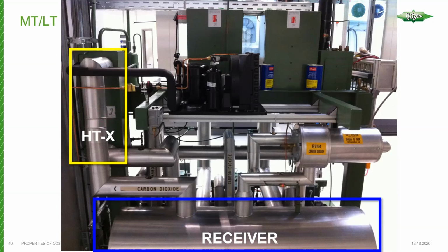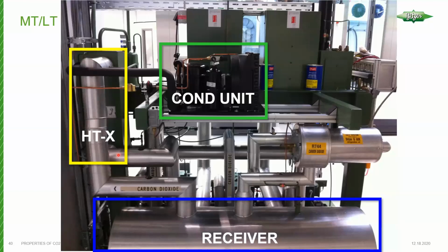And so you could have your pressure transducer determine that the receiver pressure has increased above some pressure such as 450, 500 PSI or so. That would initiate a condensing unit operation here, which would then refrigerate the vapor. Okay, so on one side of the heat exchanger, you have basically a refrigeration circuit that cools the vapor side and even recondenses the liquid. And then due to gravity, that liquid just falls right back into the tank. So that's how we can mitigate pressures in a tank like that.